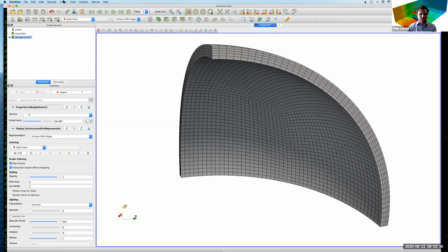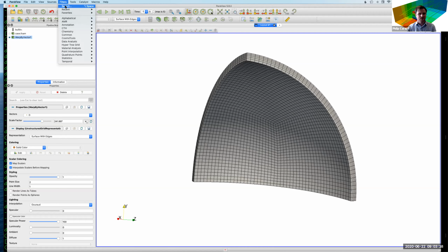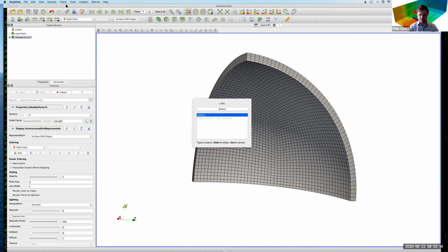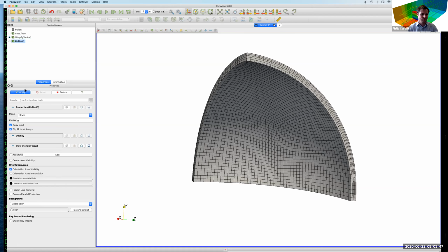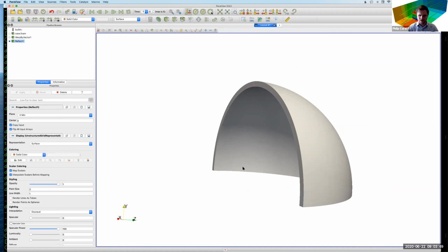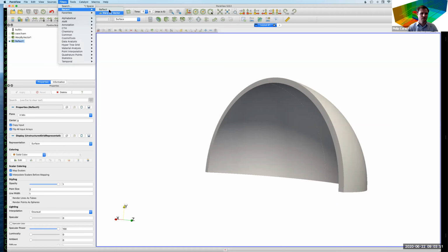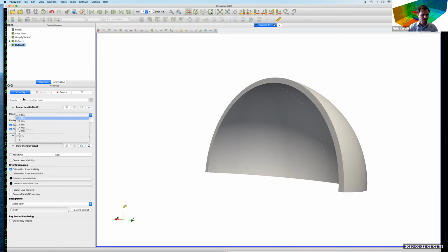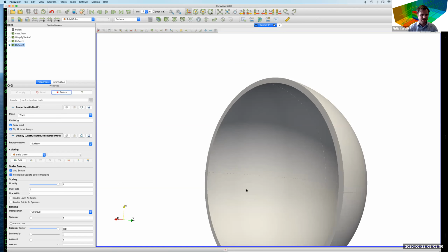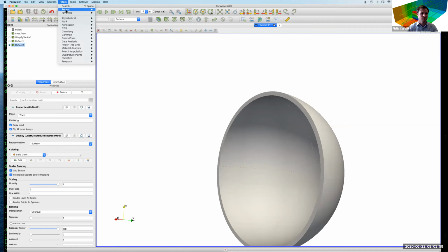This is not a ParaView tutorial. I think there is a nice ParaView tutorial by Kitware. But if you have these symmetric cases, you can use the reflect filter to generate your full cylinder if you want it. You can just do 3 reflects.